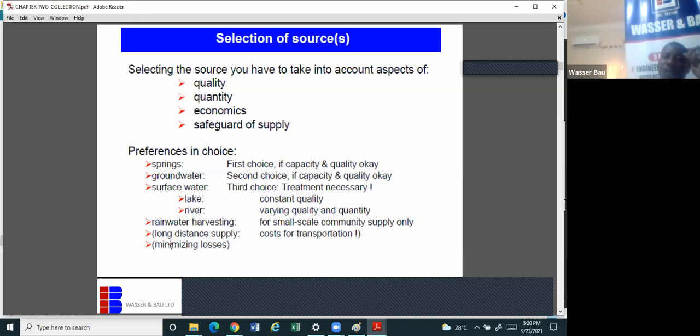Can anyone tell me, in a very short answer, the difference between spring water and groundwater? Well, let me not take time. The spring water is like an artesian well. The spring water and groundwater are the same. But for the groundwater, you need energy to pump it. Whereas the spring is already under pressure, so the water is coming out. The pressure of the water is at the surface, so the water is just coming out. I know that in the western part of this country, we have a lot of spring water because of the mangrove and some volcanic activity that took place many years ago. So there are just these features and fractures in some of the aquifers there.